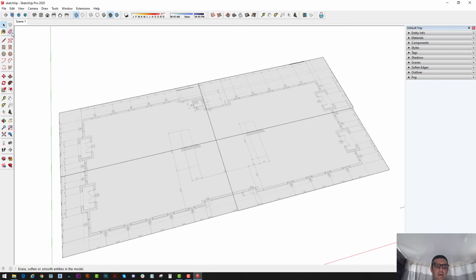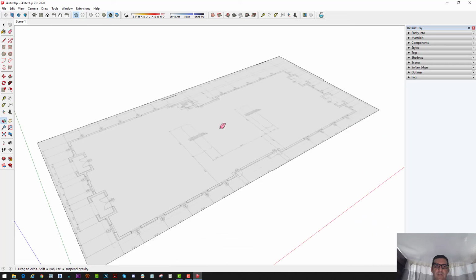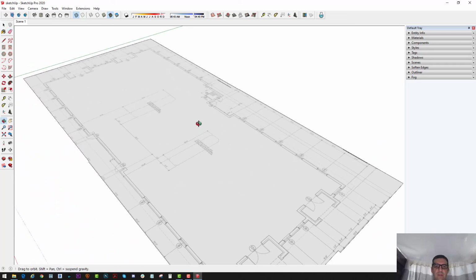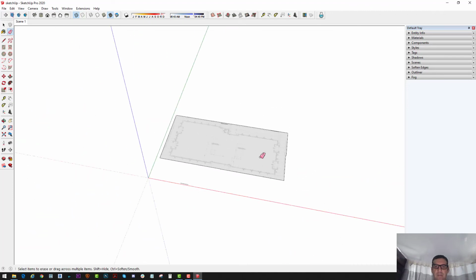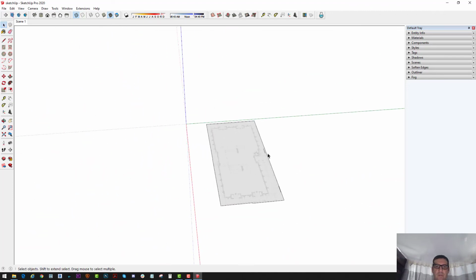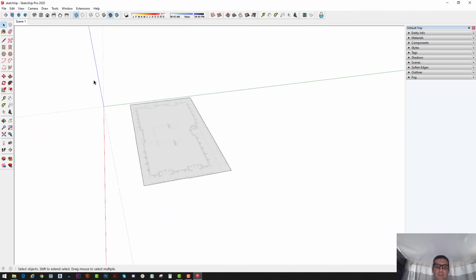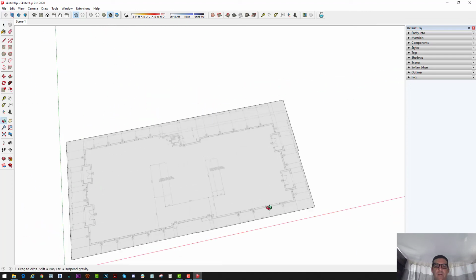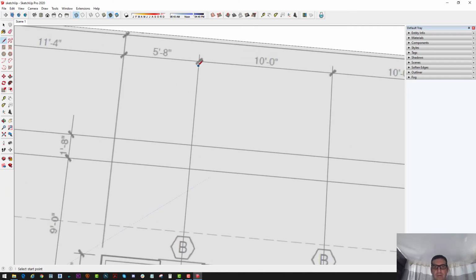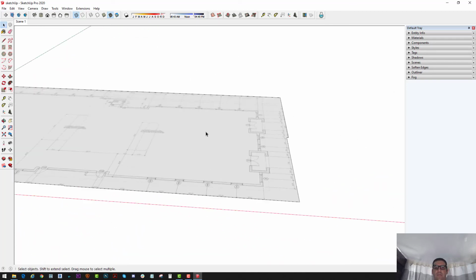And then I can click on the eraser tool, hold down shift, and then just hide those lines in the middle. Instead of erasing them, if you hold down shift with the eraser tool, it'll hide the lines. So these are my extra scale lines. Okay, so I've got the plan scaled properly, so that if this is 10 feet, then that's a proper, yep, it's very close. So it's a sloppy way without Photoshop.